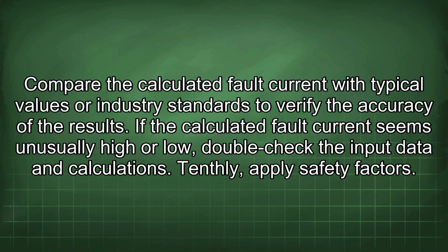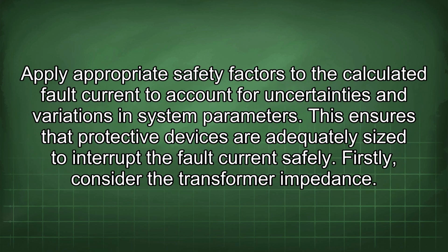Tenthly, apply safety factors. Apply appropriate safety factors to the calculated fault current to account for uncertainties and variations in system parameters. This ensures that protective devices are adequately sized to interrupt the fault current safely.